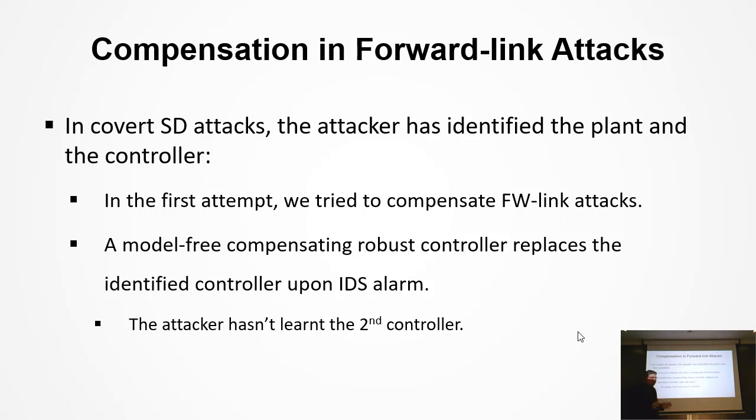Remember that in covert attacks, the attacker has learned both the controller and the plant and has tuned the attack parameters in a way that the output, the effective attack, remains in the unnoticeable range. Okay? So to compensate, we used a model-free controller, hoping that since the attacker hasn't learned the backup controller, it was never in the loop, it can manage to bring the attack side effects down.